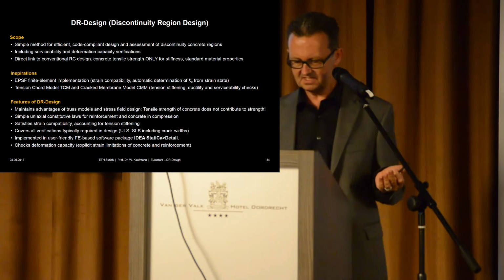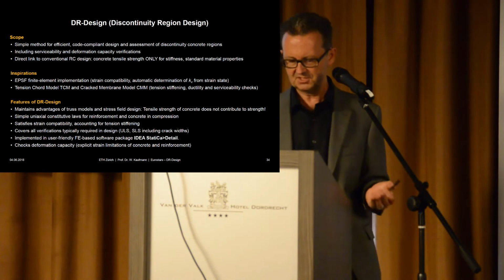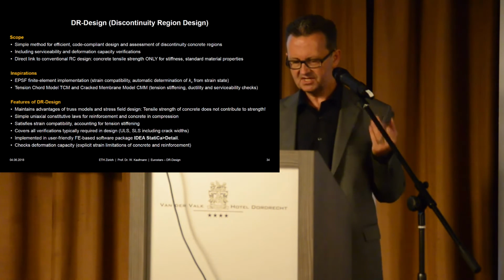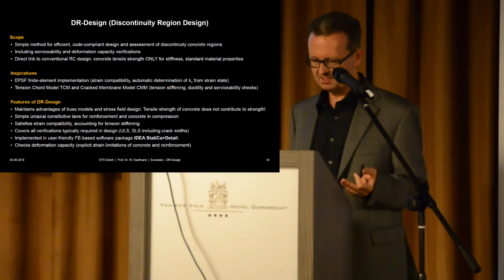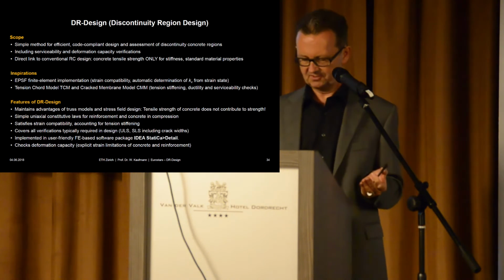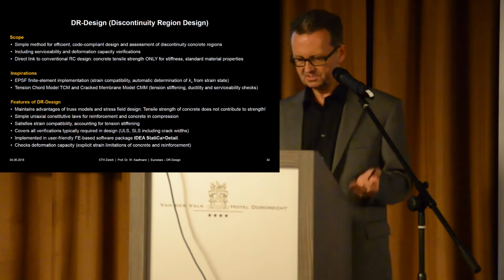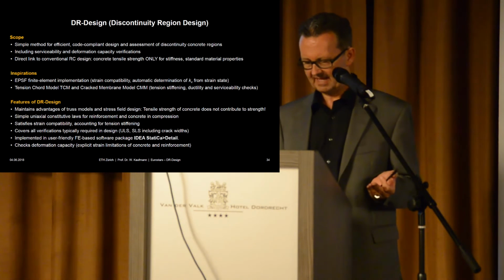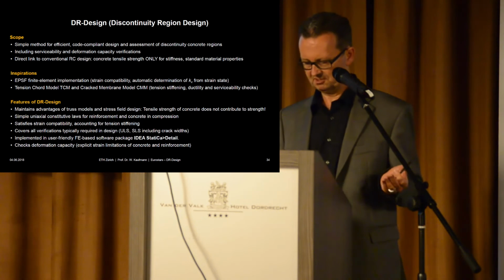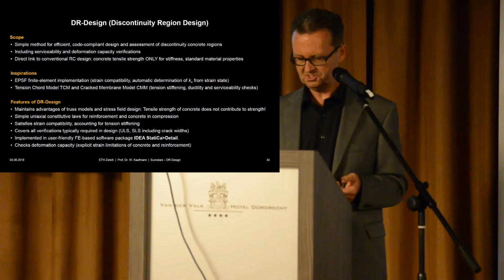So the features are that we maintain the advantages of the truss model and stress fields. We use very simple uniaxial constitutive laws. We satisfy strain compatibility, accounting for tension stiffening, it covers all verifications, and it's implemented in a user-friendly finite element-based software package. It also checks the deformation capacity.